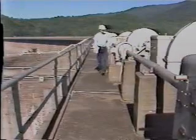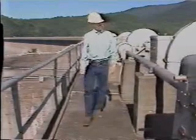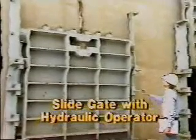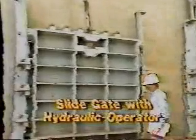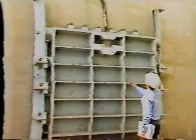Although there are many other types of gates, you will basically be looking for the same types of deficiencies, and many of the inspection techniques will also be the same. Let's contrast the radial gate inspection with one of a slide gate with a hydraulic operator. As before, the gate has been dewatered for inspection. Slide gates often serve as control devices for outlet works. Slide gates have many moving parts, which can become loose or damaged.